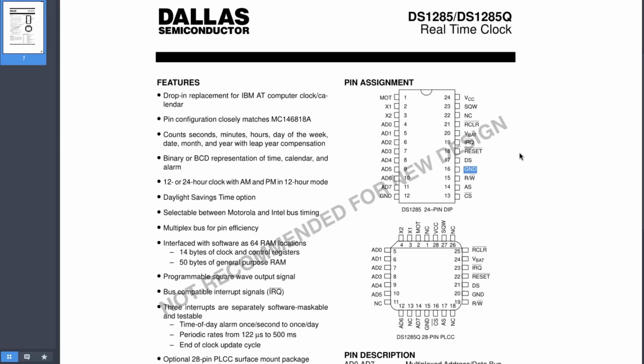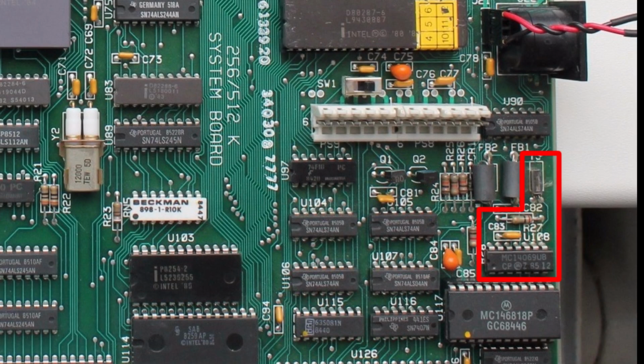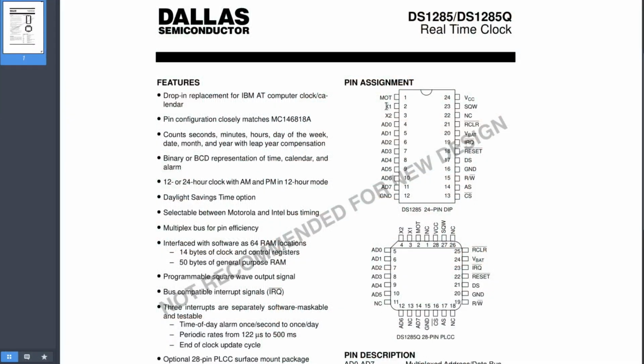The VCC pin 24, which previously was used to power the IC from an external power circuit, was replaced by a normal 5-volt power supply. Now the RTC chip got two inputs for the power supply, one from the main and one from the battery power supply, and the circuit to switch between those was moved from the mainboard into the IC. The same procedure was applied to the oscillation part, and now only an external crystal oscillator was needed on pins 2 and 3.